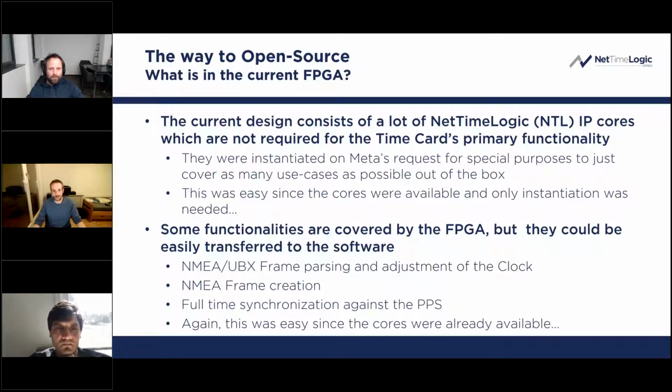In addition, some of the functionality could also be covered in software. For example, the frame parsing is now done fully in hardware, which is sometimes a bit of an overkill for just analyzing data coming via UART. This could easily be done in software. Also, adjustment of the time of day information of the clock could easily be done in software.